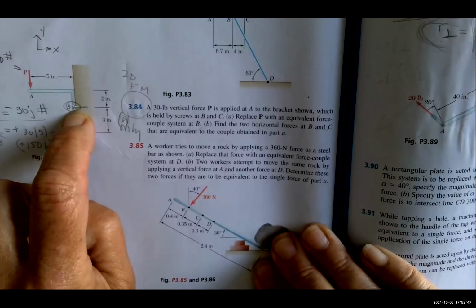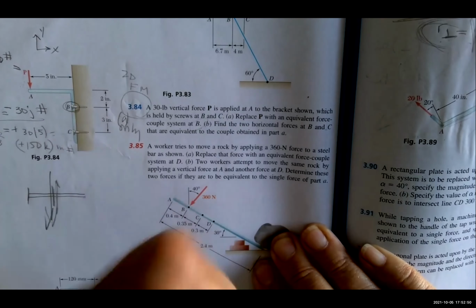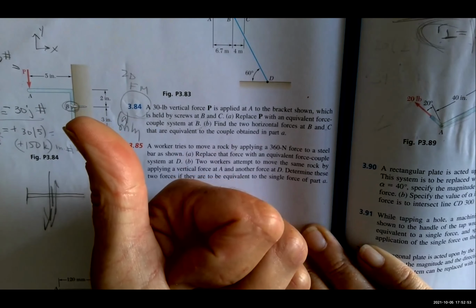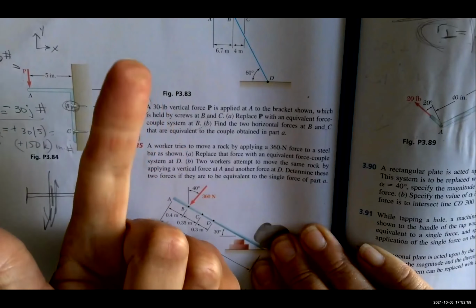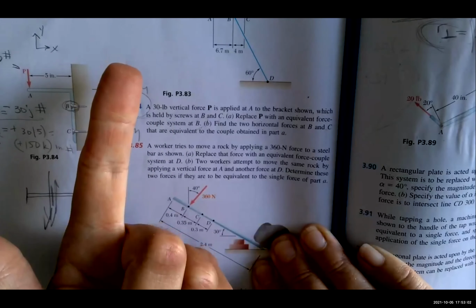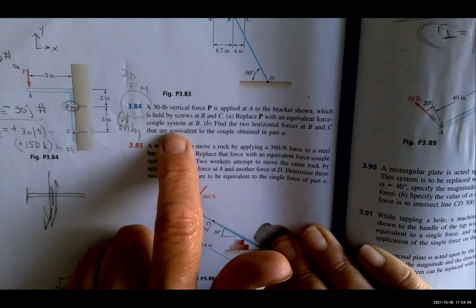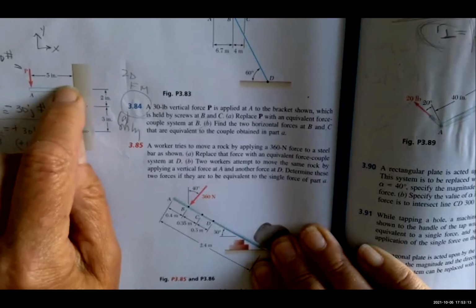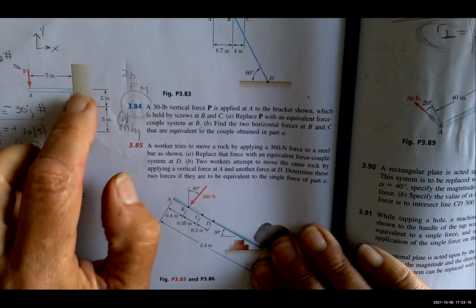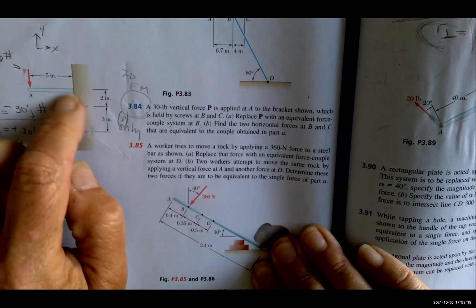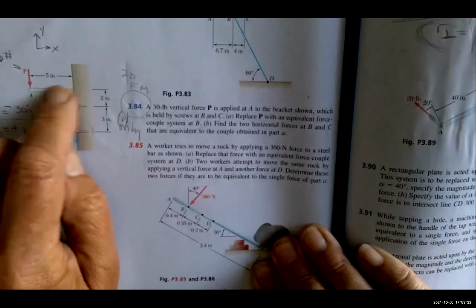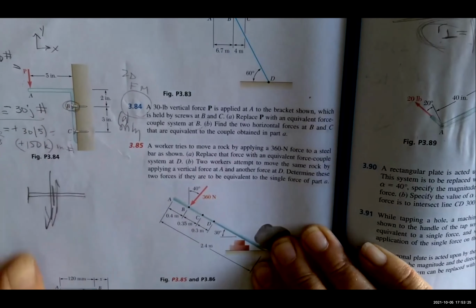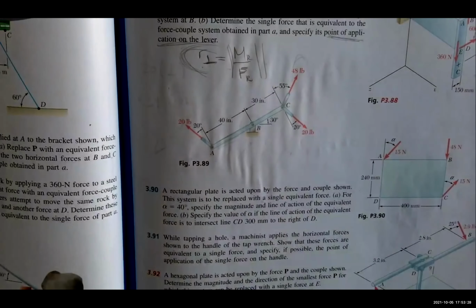Mackenzie, what do you do first on these problems? First, you find the resultant force, then find the resultant moment. Then, since this is a force moment system, what's the third step on a force moment problem? You draw the bar. Just draw the bar. Don't draw the wall too, because the bar is what's in question, right? So you draw the bar and then you draw the force and the moment at B. Great. Okay, Makana, you're next.